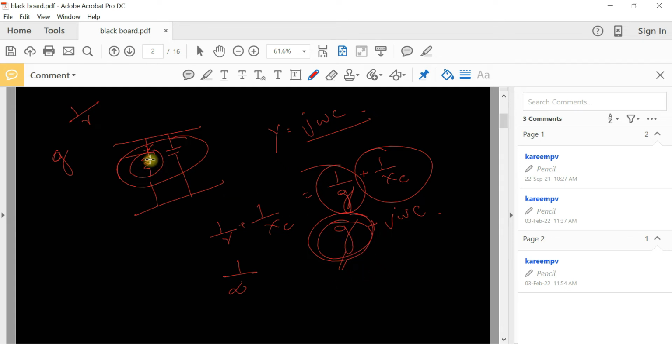And for this lossless transmission line, in this analysis, we are considering the resistive component of the shunt element as infinity. But if you consider the series element R plus j XL, so this is the series element, you have a resistive component and an inductive component. So if this transmission line is lossless, since this is a series element, you have to consider R is equal to 0.